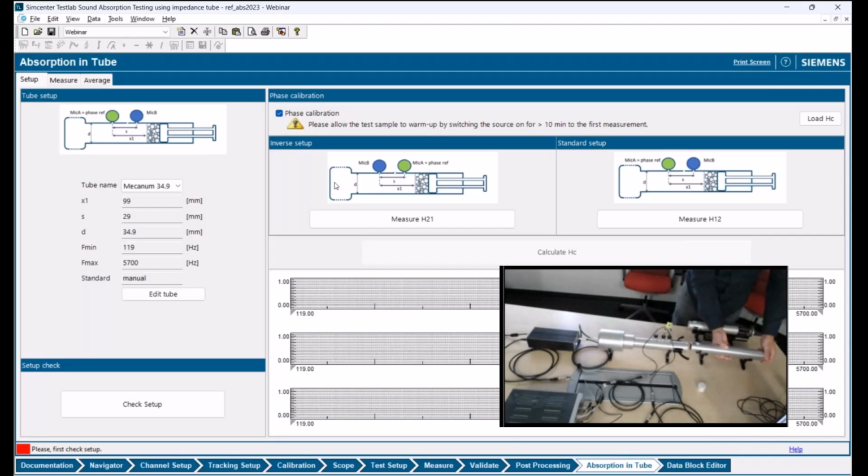These 3 pieces of the tube would come with a purchase. This is the speaker, microphone holders. This is what we call an anechoic termination. There's a bunch of foam in here and then a rigid termination. Essentially, the foam is engineered so that all the energy that enters here gets trapped or absorbed by the foam. I'm going to hook that up. I just slide that in here and put these clips on and I'm ready to go.